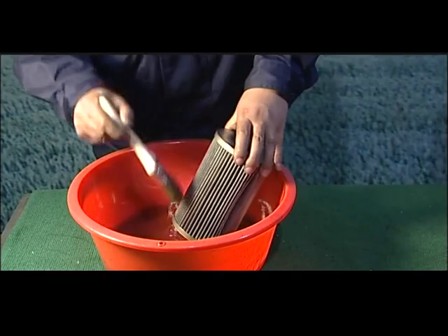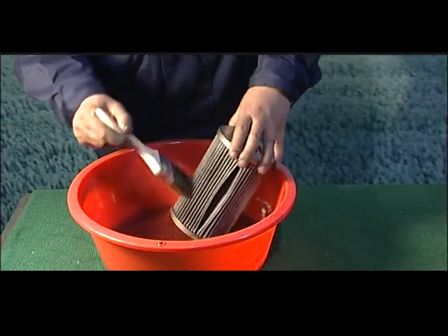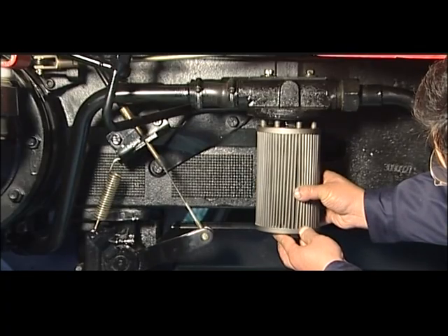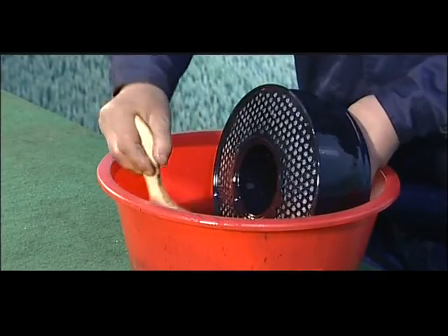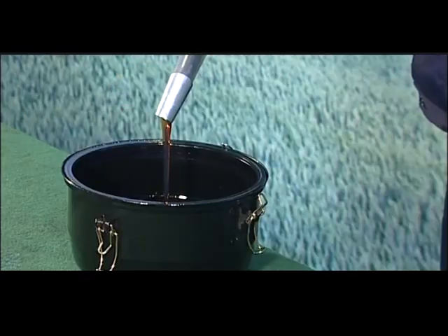200 hours technical maintenance. Complete all work of 50 hours technical maintenance service. Clean the oil filter of hydraulic lifter. Change the filter core when necessary. Clean the air filter core and refill with new oil.